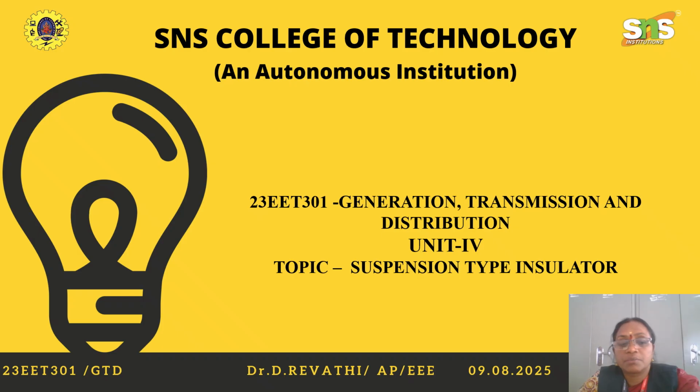I think you all remember shackle type insulator is round in shape and it has a tapered hole in the center. Because of that, we avoid breakage under heavy loads, and it is used on the low voltage side. The material is porcelain, and nowadays its use is reduced because of the move to underground cable. So this is the information we learned in the last class about shackle type.